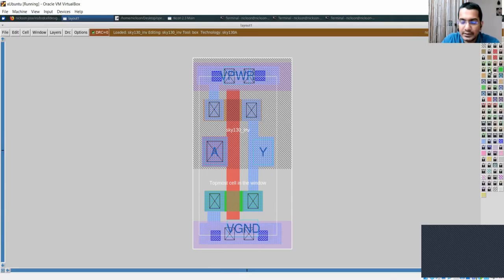If you still look into this surface topography, you still see these hills and valleys present over here. So the next step is to polish this and get a flat surface, and the step is referred to as chemical mechanical polishing, a CMP technique. This is primarily used to planarize the wafer. It's a simple technique where you take the structure or the substrate, turn it upside down, and expose it to a machine which planarizes the surface.